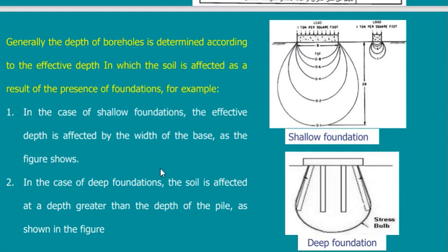To determine the depth, I have to know why I'm doing the borehole. I'm doing the borehole to study the area that will be affected by the new load. If I have a foundation, then this foundation is supposed to exert a big additional load on the ground. The ground already has some loads, maybe its own weight, maybe the weight of something next to it, anything that exerts load on this area. But my new building is going to exert new load. It will add.